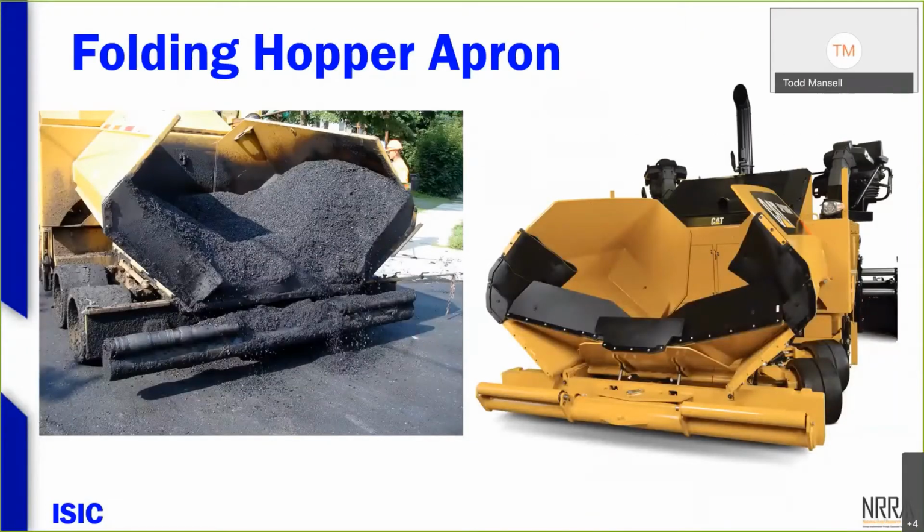So that's just an operational best practice again. If we are folding the wings, and I always get people saying, can we fold the wings? Yes, no, good, bad. If you do it properly, it's not a problem. I would almost argue in a lot of cases it's better to do that, but do it well. Make sure the flashing on the paver is working properly and not all beat up and mix is spilling in front of the paver. If you do it well, generally you can put down a good uniform mat.